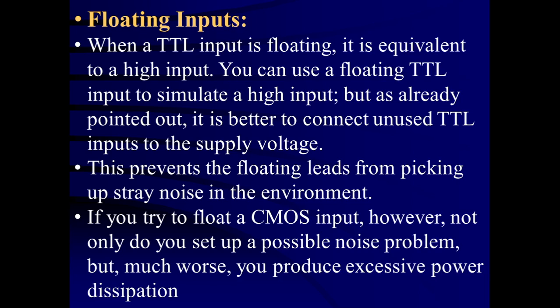Here it is not only producing false triggering, but also this floating input gets excessive charge deposited on it, and that destroys that particular device because of excessive power dissipation. So let us read through this PPT. Floating inputs.